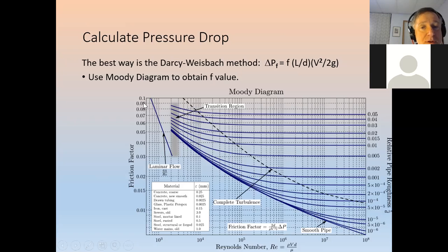Yeah, that's true. But laminar flow occurs at lower velocity. So low velocity flow has less pressure drag, or delta P if you look at this term. To see, you have the velocity squared term there. So if you want low drag, you want low velocity. That's the end of it. You're done. You don't care about boundary layer and all this stuff. You want low velocity. Well, in the real world, you want to move things often.